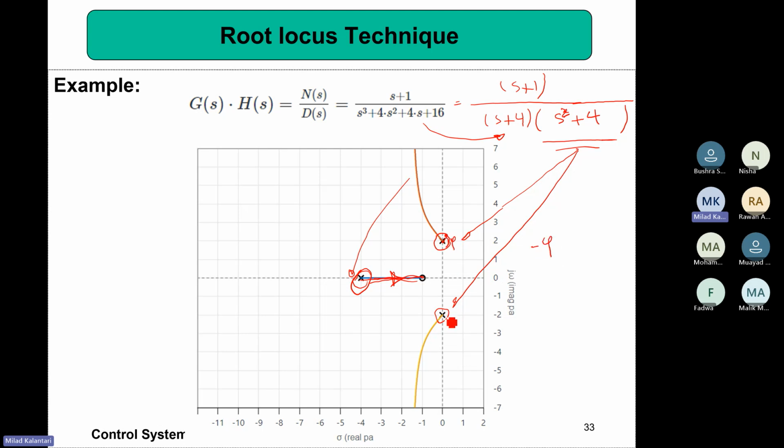From this pole it is kind of 90 degrees, right? -5/2. From this point to this 0 is how you need to calculate the angle of this triangle, right? It might be positive pi/3. Why positive? Because I am measuring from a 0. For the 0, the phases are positive. From the poles they are negative.